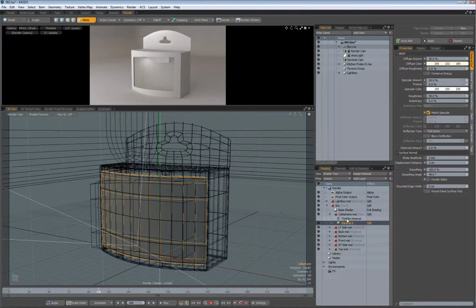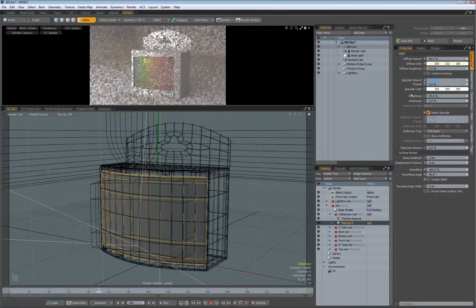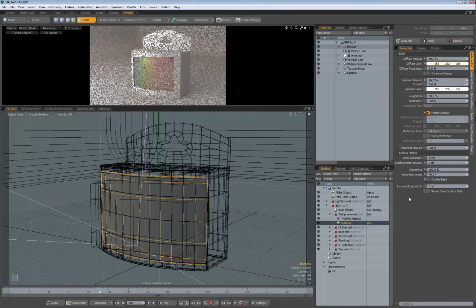So now let's turn on the thin film. And you can see it's giving us that nice colored gradient we want. It's a little harsh. And what we need to do is turn that down a little. And the way we can deal with this is to turn down the reflectivity. So we do still want some specularity. So if we turn the spec down to about 10%, you can see that that tunes it in a little bit. But it's still a little too harsh for my taste.